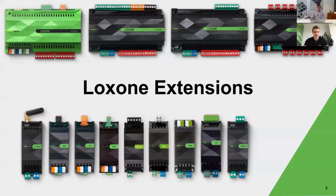So a few to just cover some of the ones you see on this page. You've got the aptly named Extension. This gives you more inputs and more outputs, so more digital and analog inputs and more analog outputs. You've got the Dimmer Extension, which gives you 4 channels of mains dimming, so 4 channels of 230 volt dimming, and again some more digital inputs on there. We've also got a Relay Extension. The Relay Extension gives you 14 16-amp rated relays. So if you need higher duty relays, the Relay Extension is your go-to.